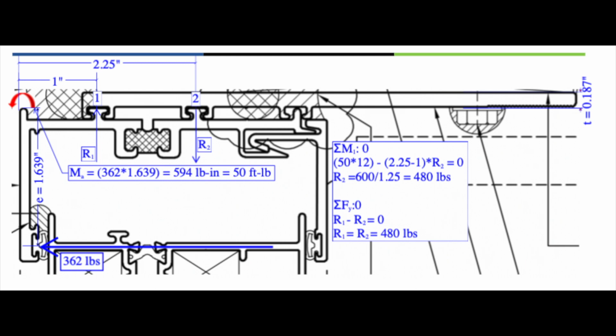One thing that Stuart mentioned is that we can assume that the strap anchor at the very left end of that figure is going to be seeing kind of like a point support thanks to that shim. That's why we typically assume a non-compressible shim. So it would be safe to assume that at that left end point you have a point support.